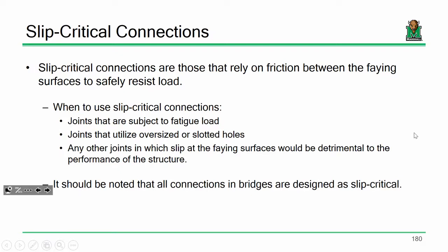Quick question. What's one type of structure where you think fatigue considerations are going to be an issue? A bridge. A bridge has cyclic loading. It sees loads over and over and over again. Now, it's not like the lawnmower where all the vibrations happen over a very short period of time. It's drawn out over years and years. We're not really talking about vibration, but it is seeing cyclical loading over an extended period of time. So we have to ensure that those connections are super tight to facilitate performance throughout the design life. That's one instance. Another is earthquakes.